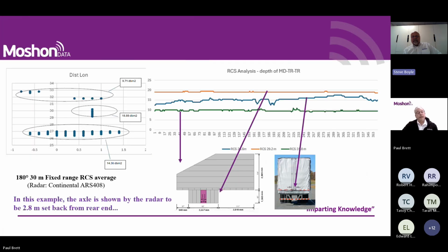With the radar cross-section values, you can see the plots here that we're getting the signatures at the rear end, obviously, because that's the first thing the radar will scan. Then it will see the axles and identify with that, and you can see in the plot of the graph here the values we're getting, and the readings we were taking at those points, and then we get a lower signature at the rear end. The slope here obviously reduces that signature quite a bit, which is part of the idea behind it.